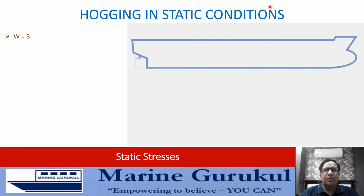We know that when the ship is afloat, freely floating, displacement has to be equal to buoyancy. In this diagram on the screen, you can see the ship coming up. It's floating at the water line, which is now shown on the diagram. Now we'll divide this ship into three distinct parts: one forward part, one middle part, and one after part. As you can see now, you have the forward part, middle part, and after part. And of course, the displacement of the ship W will have contributions of the weights from the forward part, from the middle part, and from the after part.